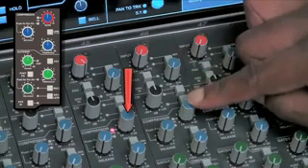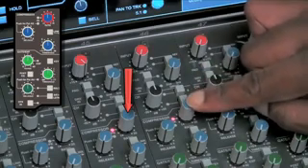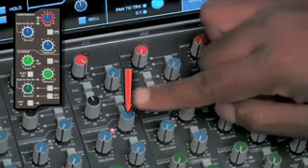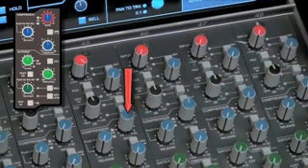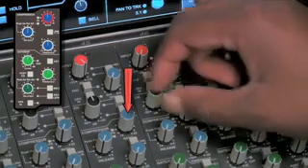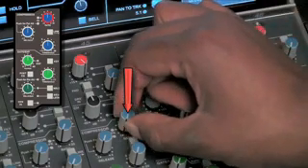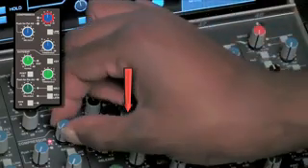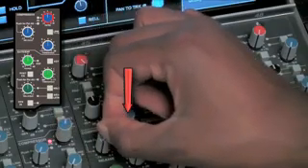Pressing the ratio pot changes the compressor to peak mode. As you can see, the PK LED lights up. This indicates that the peak mode has been selected. This replaces the soft knee characteristic of the compressor with a hard knee, and this provides alternative voicing for some instruments. Next, we'll talk about threshold.